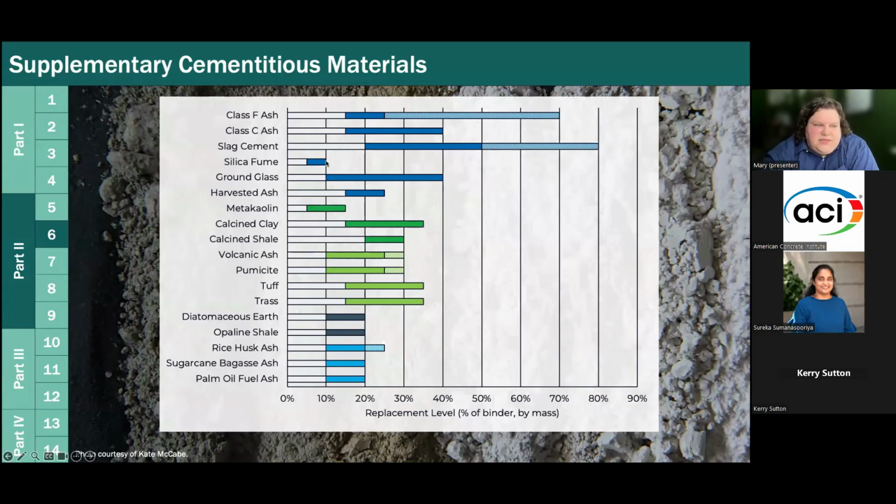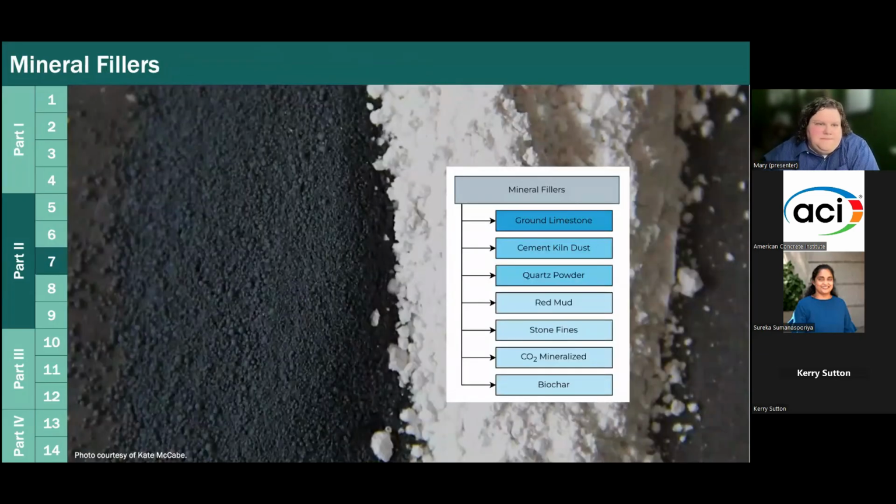And so with SCMs, just be really careful and take a little time to explore what that material is and what it should be used for. And as Kelly said in the very beginning of this, test batches, trial batches, that's the way to really learn about these materials.